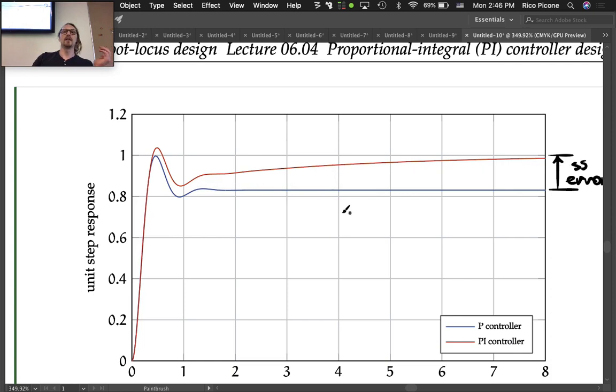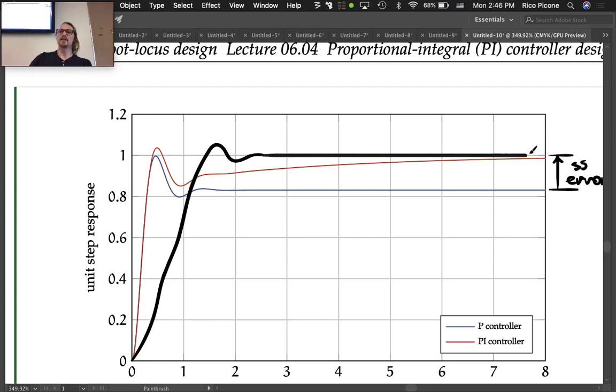And it would take a long time. So that's usually not what you want. Oftentimes what you're going to want is to get that steady state error being small quicker. So if you move that 0 leftward, usually that's going to happen. Move that 0 leftward, and you're going to pay a price. I'll try to exaggerate it a little bit. You're going to pay a price in the rise, but you'll probably get to your steady state value faster.